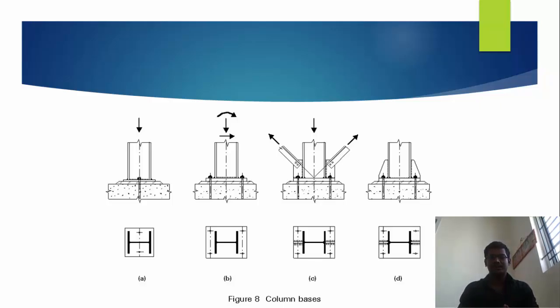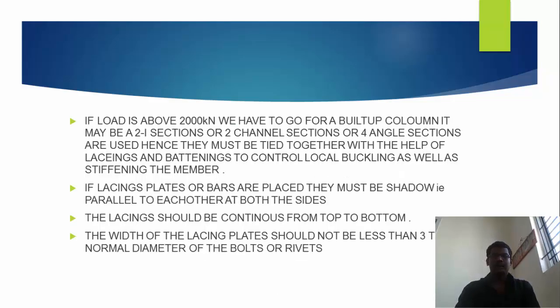The first is a normal column base fixation. The second is a base plate with gusset plate and extra cover plate. The third is the angular column plate fixation with stiffeners, and the fourth is a column base plate arrangement with stiffeners applied onto it.